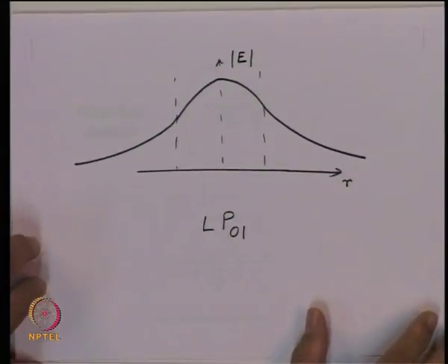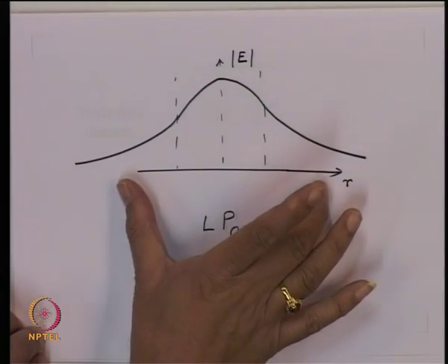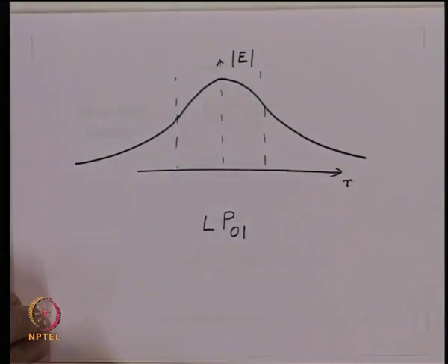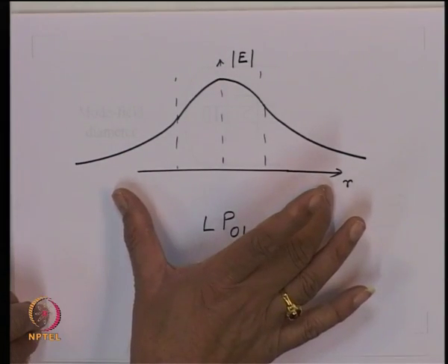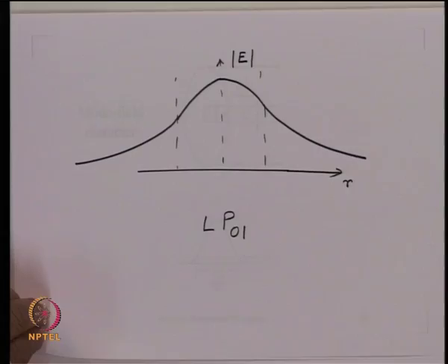So, essentially we get the field distribution for the optical fiber, you measure the diameter over which the field reduces to 1 over E of its maximum value, and that diameter we call the mode field diameter. So, for a single mode optical fiber which has a complex refractive index profile, the mode field diameter is a much more meaningful quantity than the V number, because the V number cannot be defined for these complex refractive index structures.